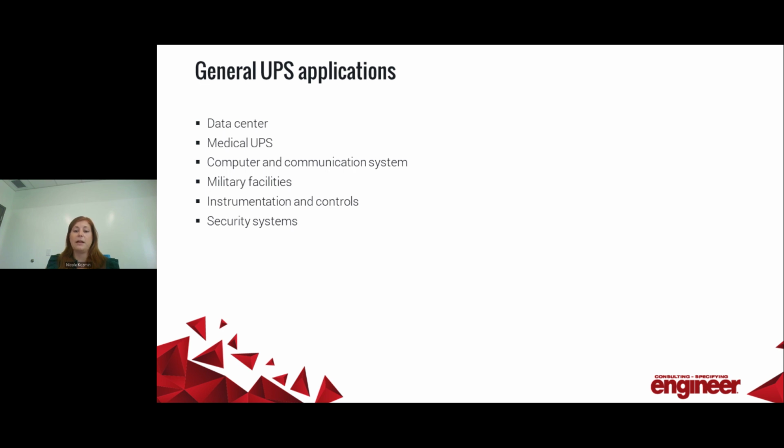For example, if you are subject to the requirement for a disconnecting means to be provided for IT equipment and associated HVAC systems per NEC 645.10, you can utilize shunt trip breakers in your AC panel and connect them to an emergency power off switch near the entrance of the room.